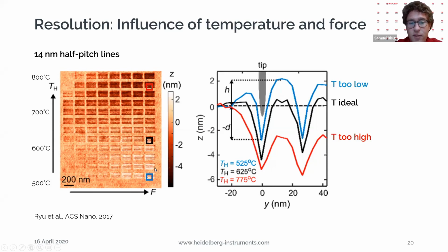If the temperature is too high, somewhere here, you can see in the cross section that neighboring pixels got decomposed because the heat flux between these neighboring pixels is too big. So you also get this kind of recess, where the resolution is lost and the final amplitude you can transfer is shrunk.